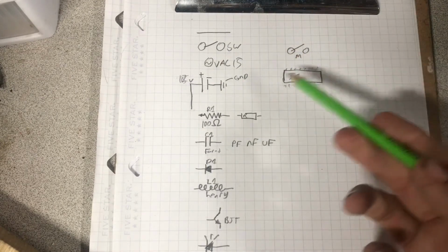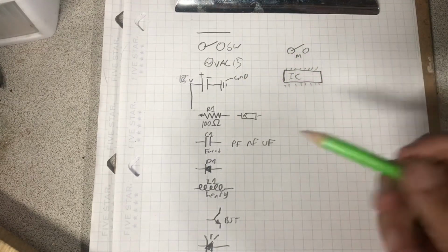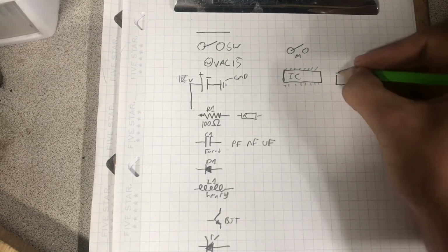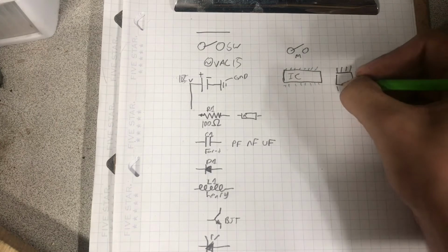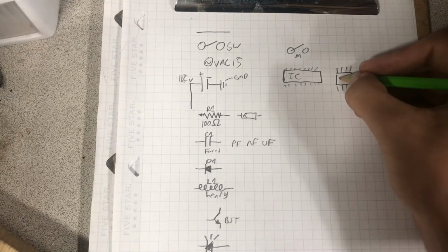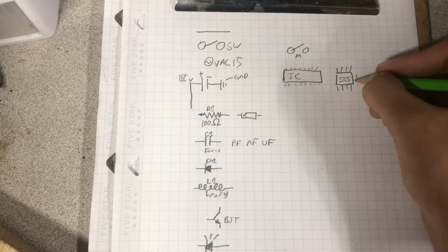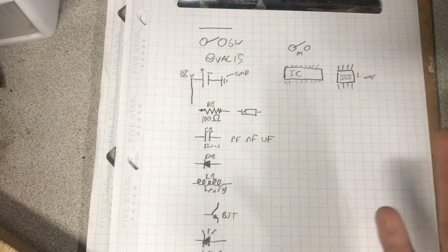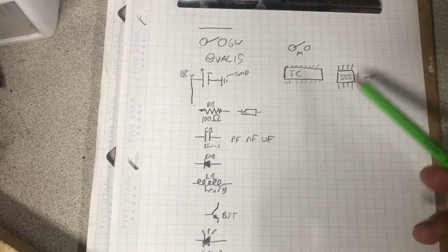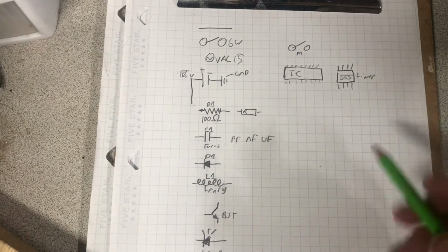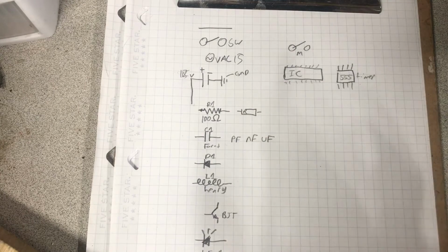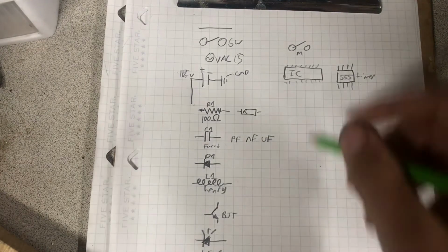Some can be for digital applications, some can be for analog applications, like one of the first ICs ever made, and still very popular to this day, the 555 timer chip, which is an analog timer, but it is very, very useful for different things. And it can switch, I think, as high as 1 megahertz, so 1 million times a second.